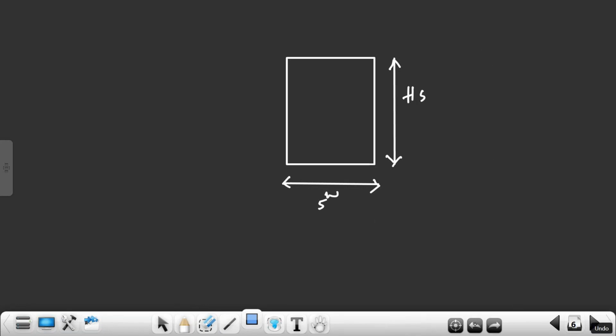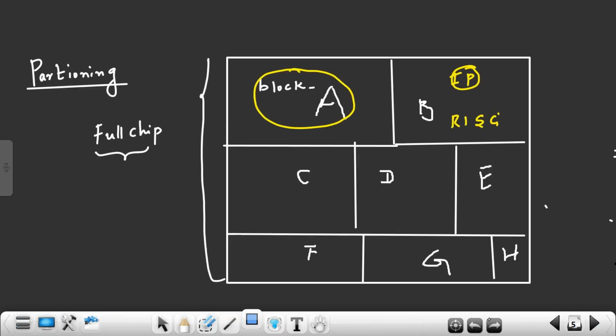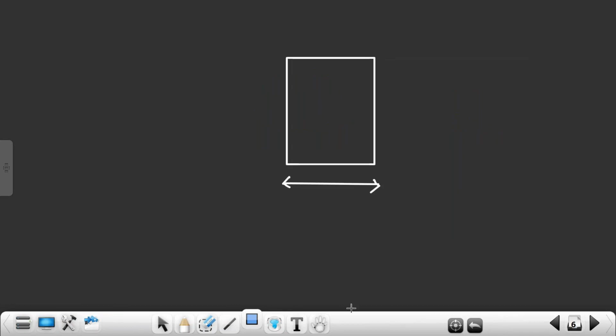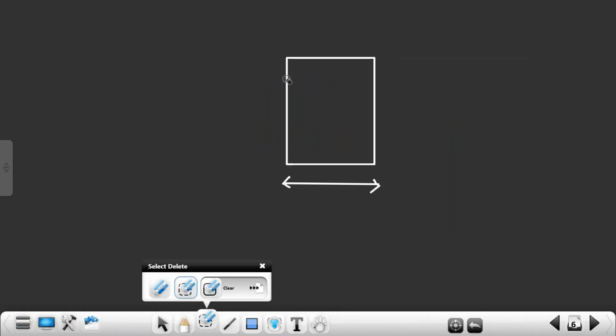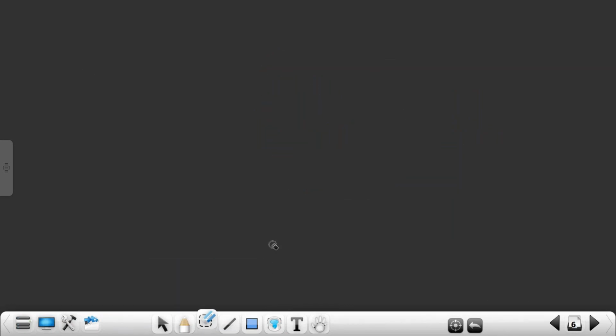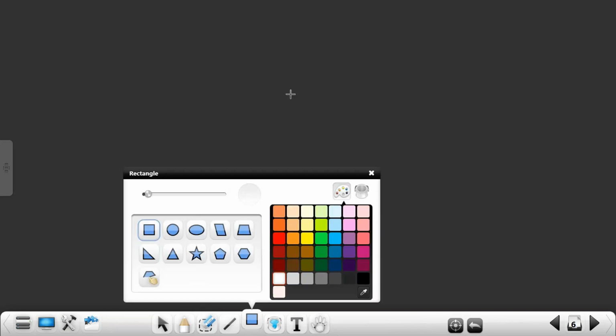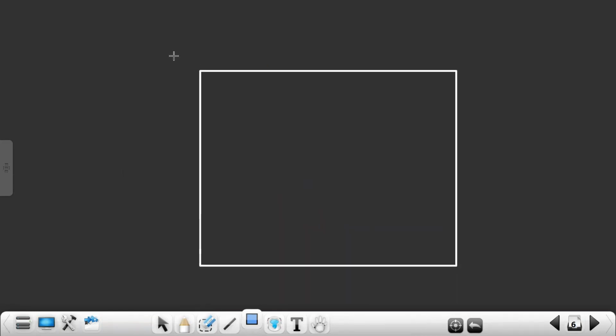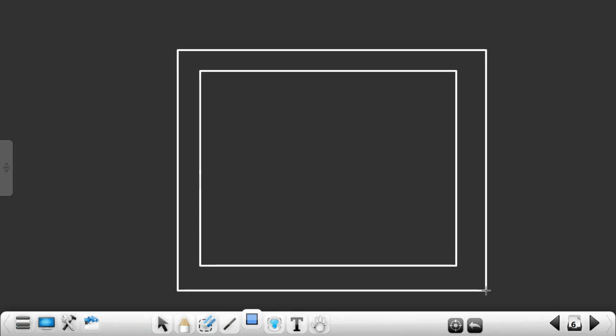So my tool can calculate the area requirement by analyzing the input files. The height and width of a cell is present in the LEF file. By calculating that, first my tool will create the core area and die area.